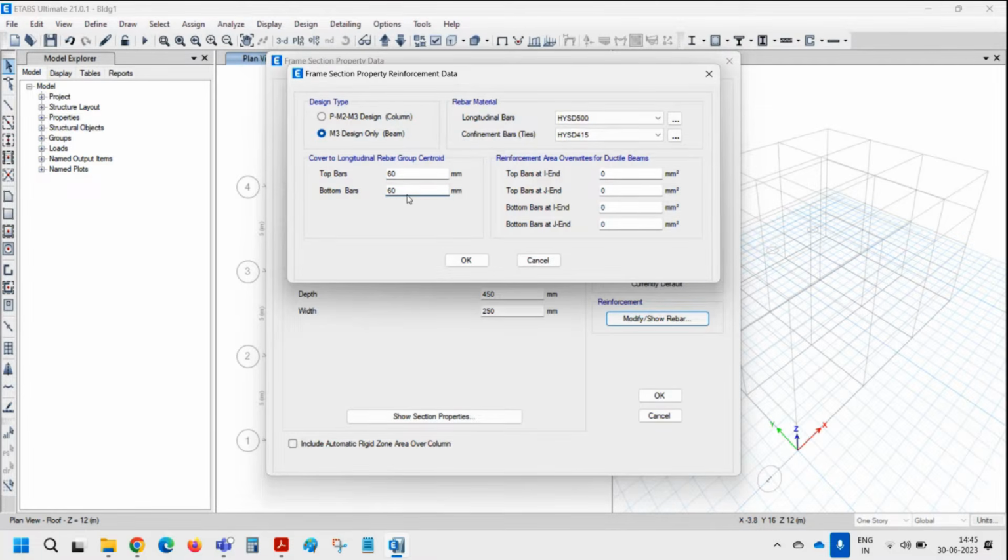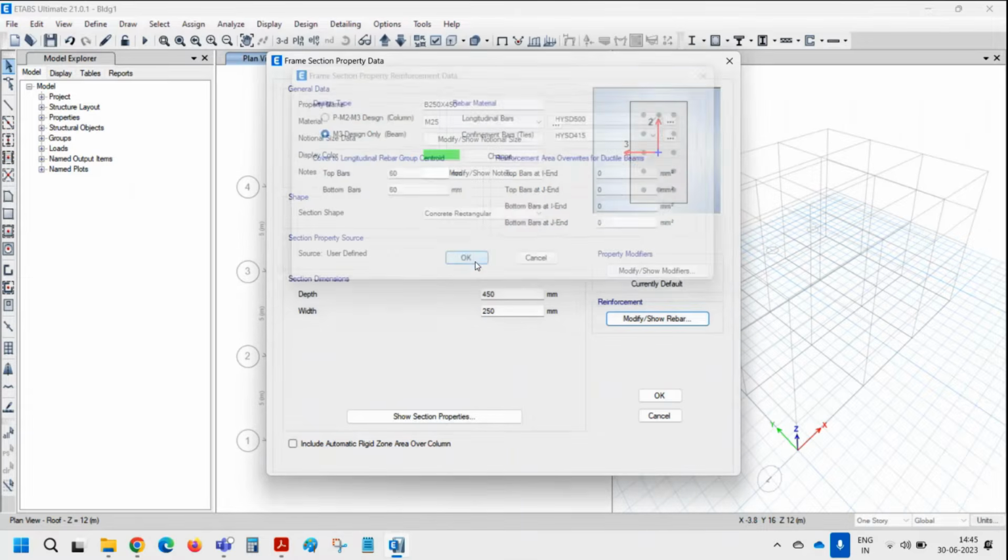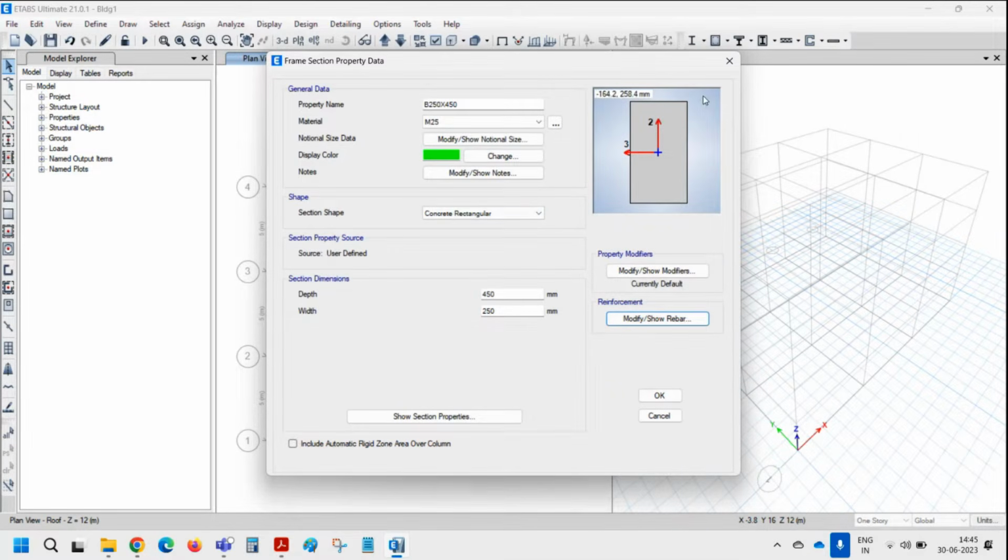So this comes from experience. We're expecting a 2-layer of rebar based on size and depth, basically, how much it is allowed, and you decide on that and specify it from experience. So I'm assuming 2 layers, so approximately 60 mm from the extreme fiber for both top and bottom. That's all you have to do here. And for a beam definition, your rebars will not be displayed.